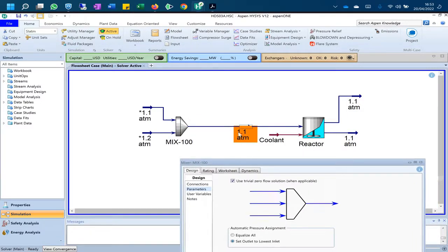Well, this is done by HDS, but this is not the case in real life, because if you connect 3 pipes to a mixer, in the real process, all pressures are automatically equalized because some flow is produced from high pressure pipes to low pressure pipes until equalized pressure is obtained in all the systems.